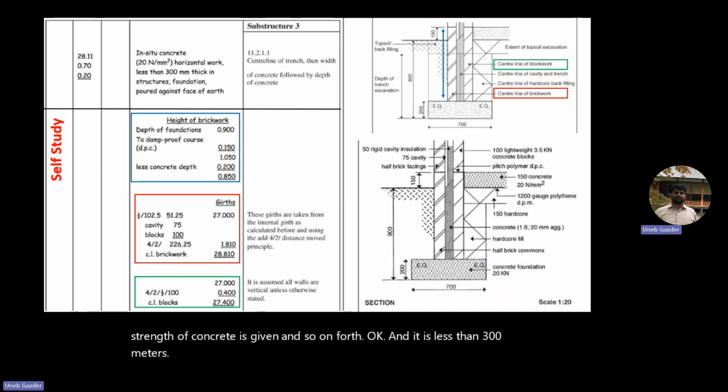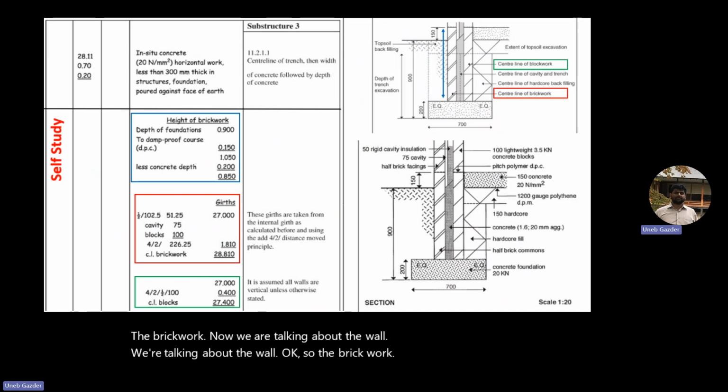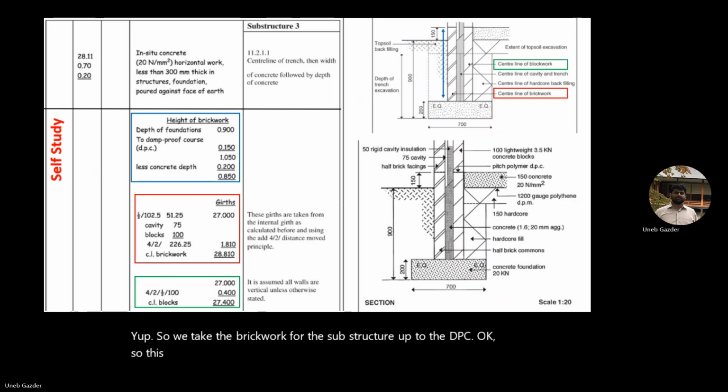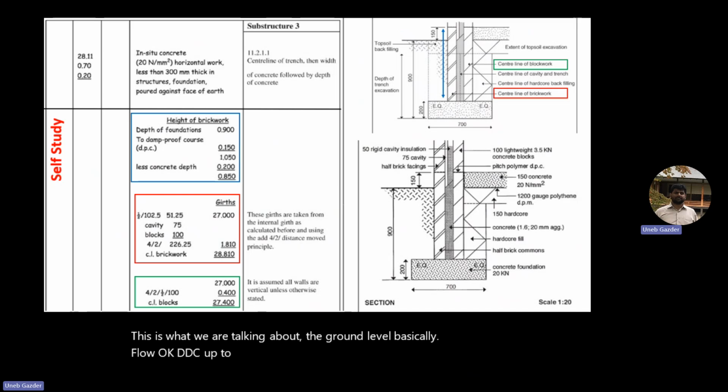Then the brickwork. Now we are talking about the wall. So the brickwork: we take the brickwork for the substructure up to the DPC, up to the floor level. Not the ground level, floor level.